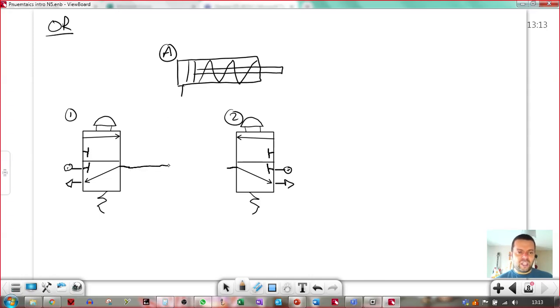So you would think that you would just do that. A T-piece in there, wouldn't you? You would think that was easy, but it's not. So don't assume that that's the answer. I'm just going to explain why that's wrong. The reason it's wrong is that if a person presses that button, what we've got is this state active. So main air is connected to this port, and we'll have an immediate increase in air pressure, and we need that air pressure to move this guy out.